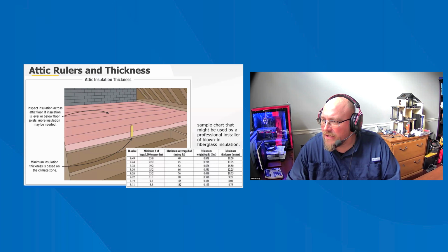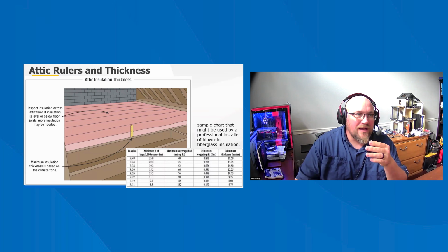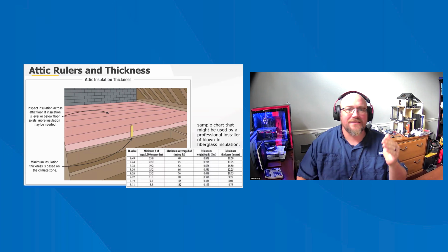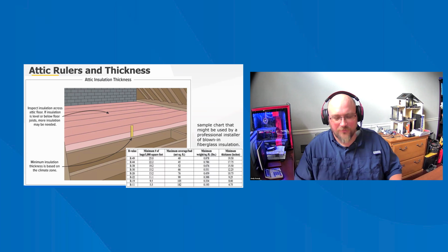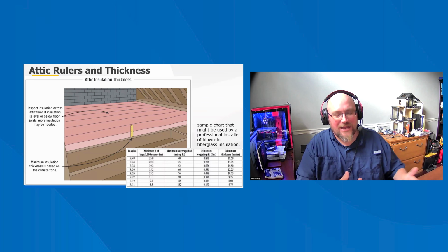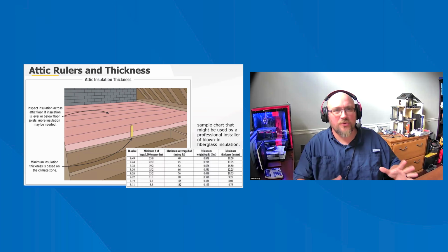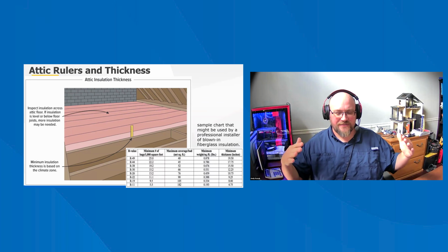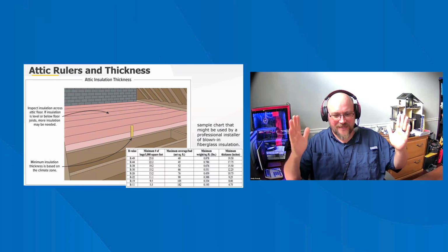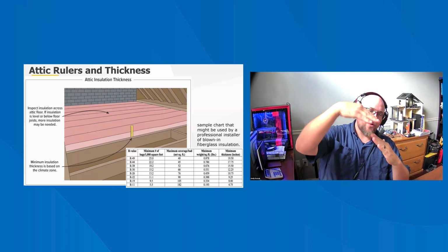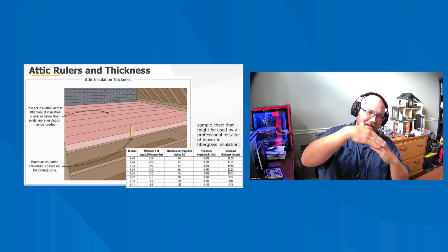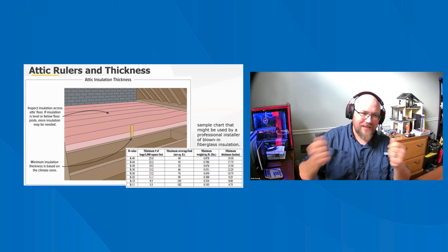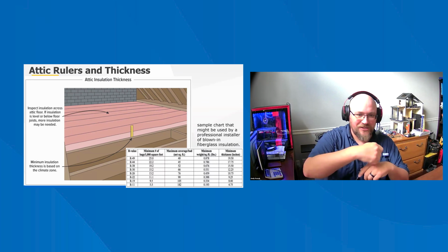Another location to keep an eye on is, not that you're required to do thermal imaging, and we're not going to hit on thermal imaging here, but thermal imaging is how I found this one section. When you have a tray ceiling, where it's not straight up and down but at an angle like this, on an exterior wall, the back side of that tray, because it was so close to the eave, even the insulation installer didn't blow insulation down in that part.